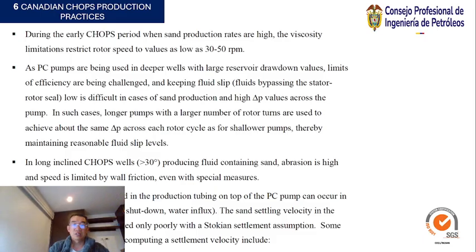Sand settling out of the fluid in the production tubing on top of the PC pump can occur in some situations, such as power shutdown or water influx. The sand settling velocity in the viscous fluid can be estimated only poorly with a Stokes settlement assumption.